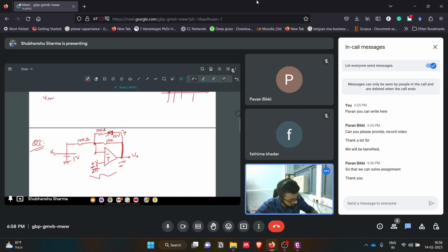So we are basically applying negative to this side of the Zener diode. This will make the Zener diode reverse bias. When the Zener diode is in reverse bias, it acts as a potential source like this. So this will be 3.2 volts. This is 10K, this is 10K, this is 1 volt. We already have one more feedback of 10K. This is minus, this is plus.